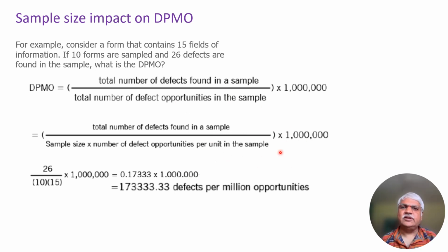However, in the case of IC design, the DPMO should be calculated in a different way. Assume that we are considering the same hold timing path. Each hold timing path scenario is different, because each hold timing path analysis is individualistic. It is not like if there are 100,000 timing paths in the design, that means you have 100,000 defect opportunities.